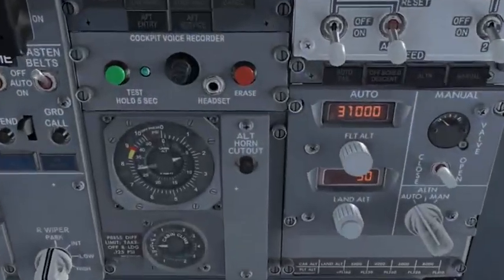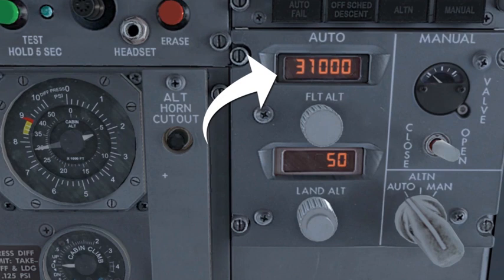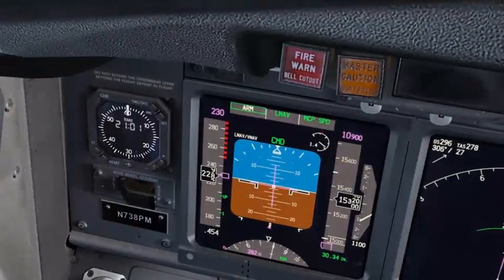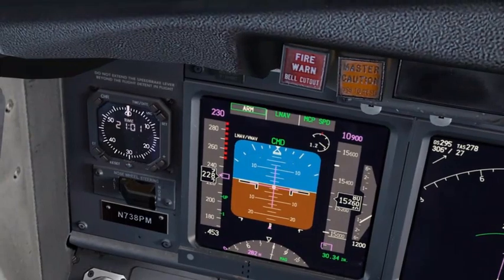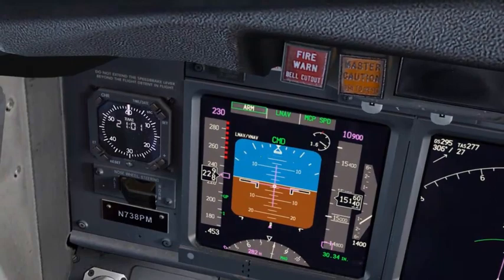To understand the cruise logic, let's go back to the flight altitude selector in the cabin pressurization panel. The pilots must enter the expected cruise level in the flight altitude selector, which allows input between 1,000 feet and 42,000 feet. While the aircraft is climbing and the external air pressure decreases within 0.25 psi of the flight altitude selection, the pressurization system switches to the cruise mode. In this mode, the cabin altitude is maintained according to the pressure schedule we talked about previously.